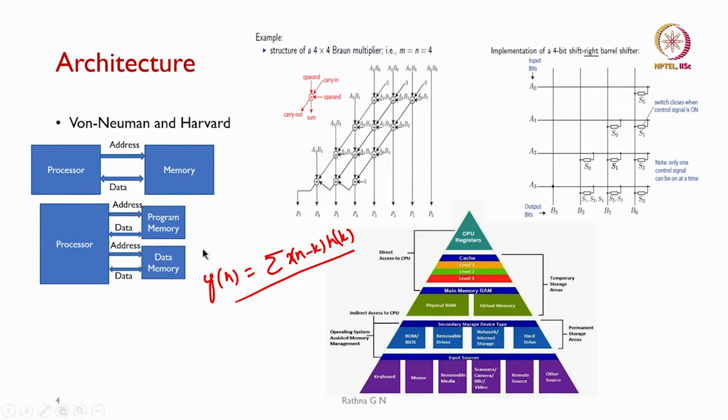So, what was decided? If we are talking about a filter, then we know that the filter is designed much earlier. In real time we will be using only those filter coefficients to pass our input through. So, these can be stored in our program memory, and the input data is going to come into the data memory, and then we can access them simultaneously.